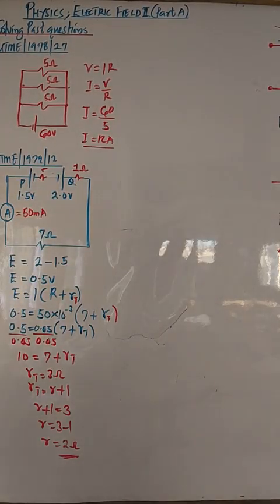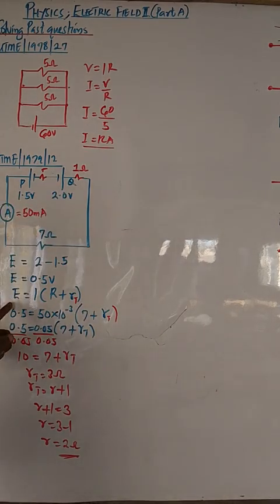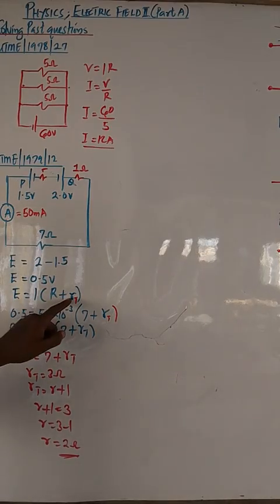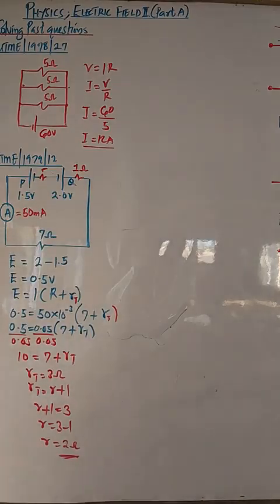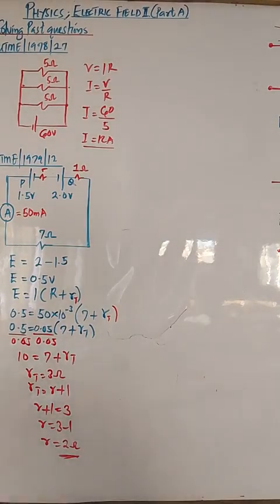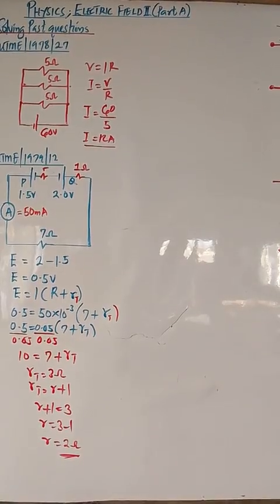Can you see? First, the terminals, and I explained in the lecture. Second, this formula. If you have only 1 cell, you have to look for the effective, which you look for here. Then RT, we've got a lot of RT here, and here RT is actually this plus this because they are in series. If they are in parallel, we are going to use parallel arrangement. As simple as that.